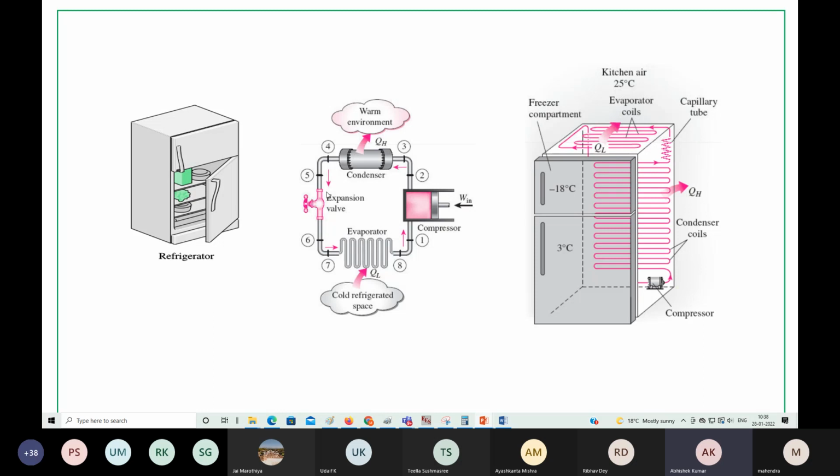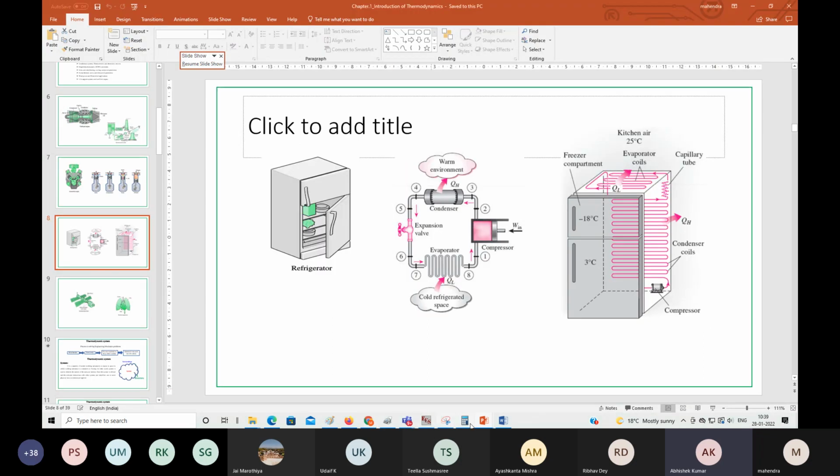This is the condenser. Here it is changing its phase to liquid. And here we have one valve actually. This is the throttle valve we can call. In your refrigerator also, at the backside you can see a very thin long tube like a coil. That is your throttle valve. What is happening when it is going over here? Because of the throttling process, high pressure to low pressure sudden expansion, the fluid is becoming cold. The temperature of the fluid is further reducing over here. That is the purpose of this, and that is the reason for this particular application.